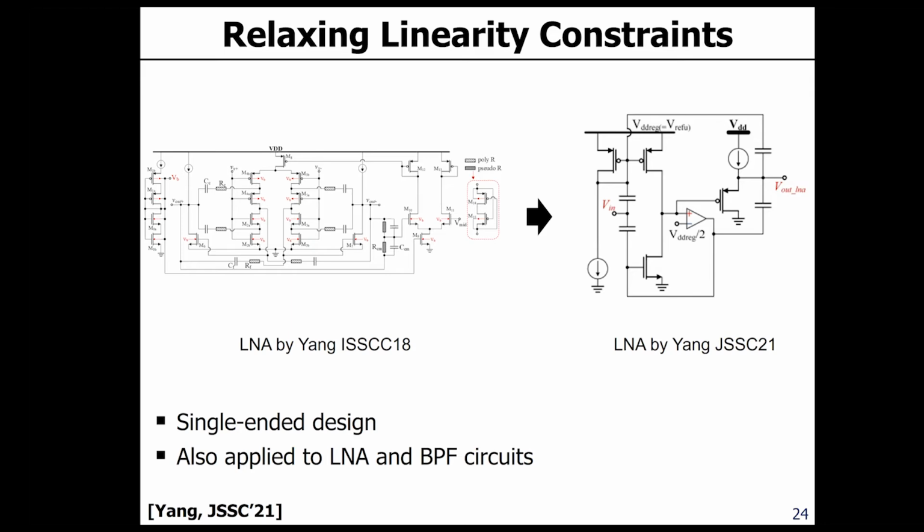And now we decide not to do the linearity thing anymore, and we take a single-ended design. We just put the LDO on top of it so that we can compensate for the power supply noise, and do a very simple design. It turns out to be orders of magnitude simpler, and also quite power saving. So we apply the same concept, getting rid of the linearity, to the design of the bandpass filters, rectifiers, amplifiers, and all the other circuitry.